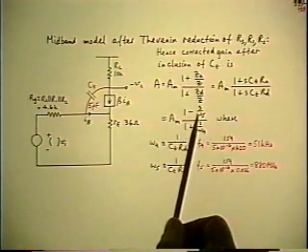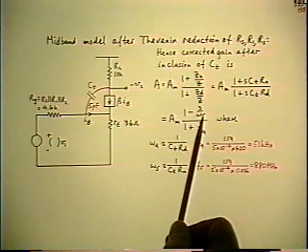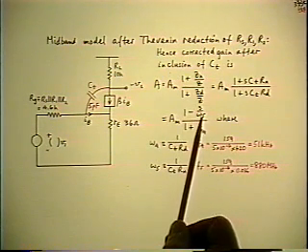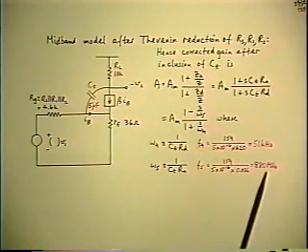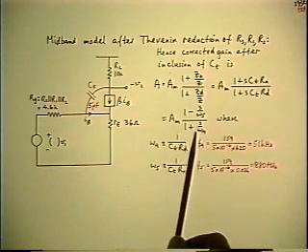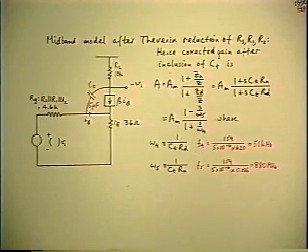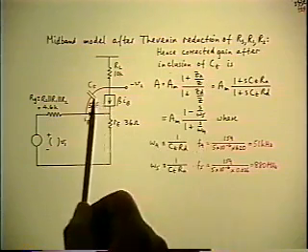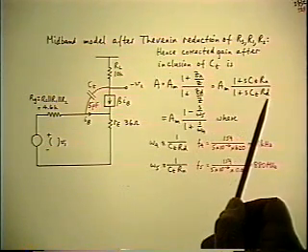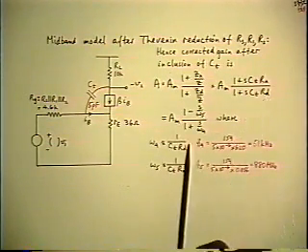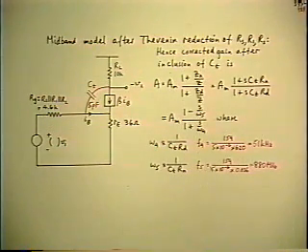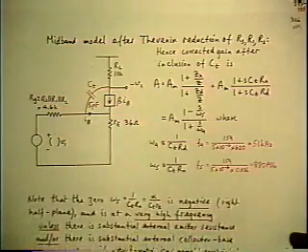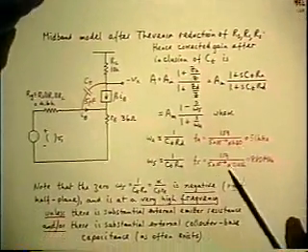Well, enough about the right half plane zero for the moment. We're still going to come back to it later on, though. But for the moment, let's dispose of it, because at least with these numbers, it isn't going to be of any concern. Now let's look at the pole. The pole is the CT with the RD. And the RD, remember, is a large multiple of the RL. So we need to look now into where that multiple comes from.